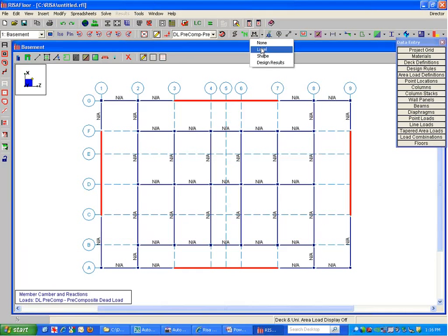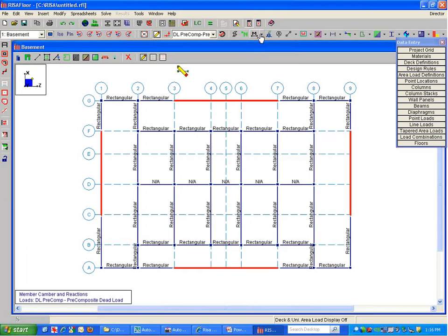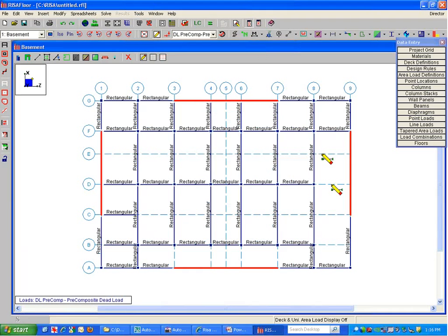The members here, the labels show me as rectangular. And then the last little pieces, I'm just going to draw in some of the pieces that didn't populate. And really what you're missing here is just the ones that go in between the walls. So I just click around, and you can see all I'm doing is clicking right on that grid, and then the beams go into place there. So I'm going to just drop in some beams here.